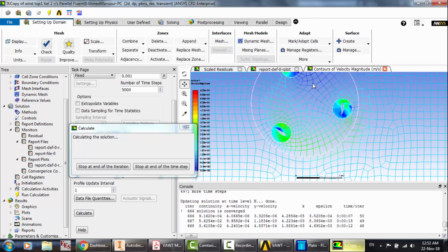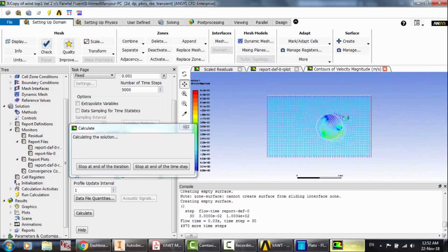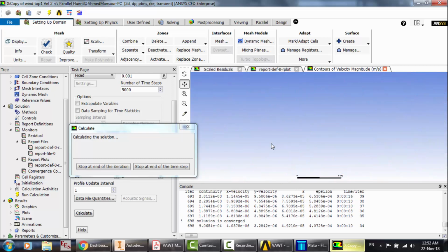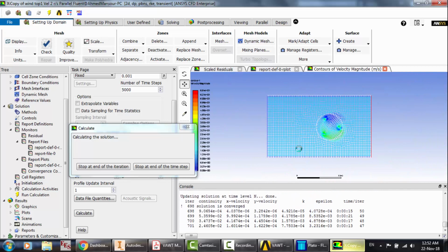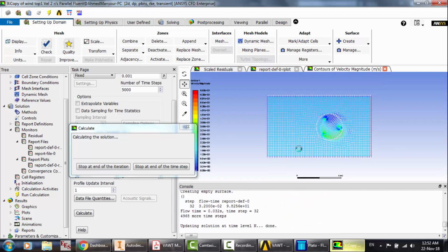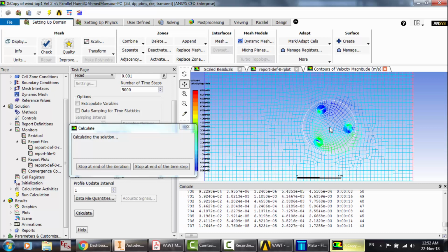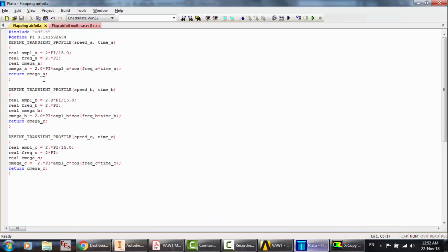Now it is 0. So what if you change the velocity or the rotating speed? Here is 13. What if it is half of 13? What if it is 6.5 and I don't want to change anything and I want to run another simulation? Just go here and change the frequency. So 6.5 divided by 13 will give you half. 1 by half is 2. So 2 is multiplied by this frequency, it will be 4.